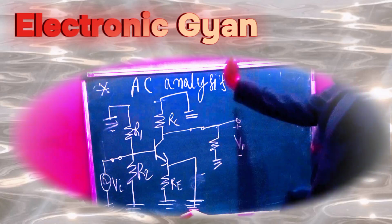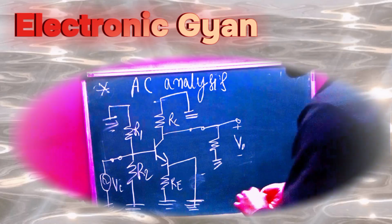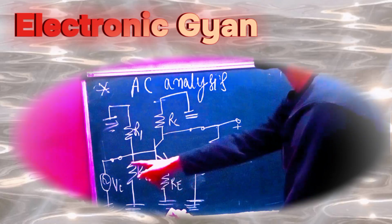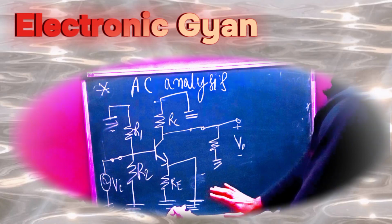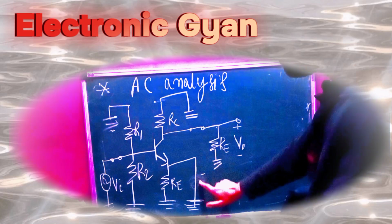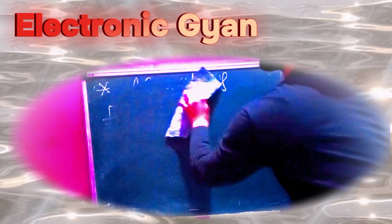Now we are going to draw the small signal equivalent circuit for this AC analysis. Let's see how to draw that. All the capacitances, both bypass and coupling, get short circuited, and the emitter resistance gets bypassed by the bypass capacitance. Therefore the small signal equivalent circuit will be obtained as follows.